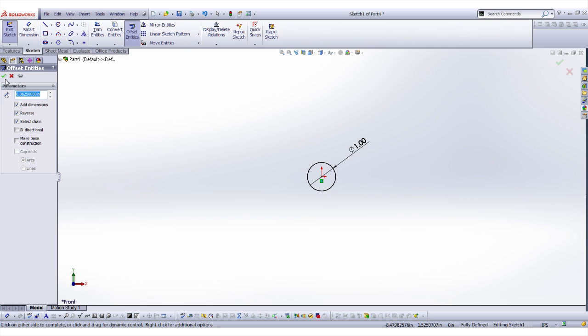Wait, did you say you made a 15th, 16th circle? Ian, what's your wall thickness on a 15th inside dimension tube with an inch outside? Oh. This is why you measure things, because your tube is wrong. You have a 32nd inch wall tube.